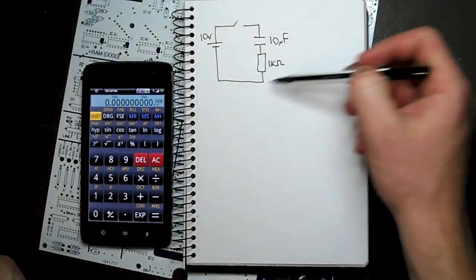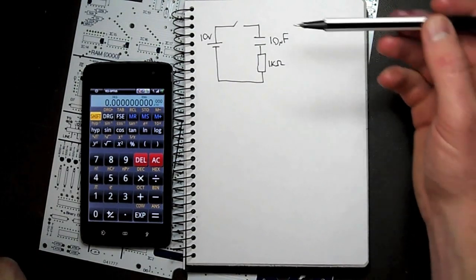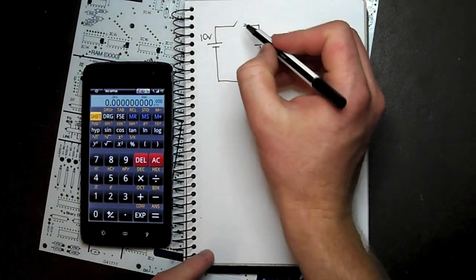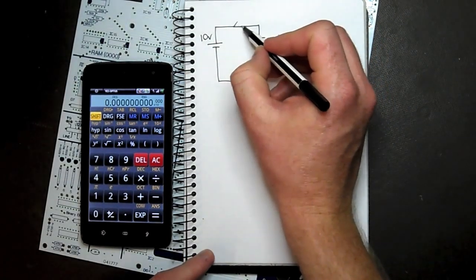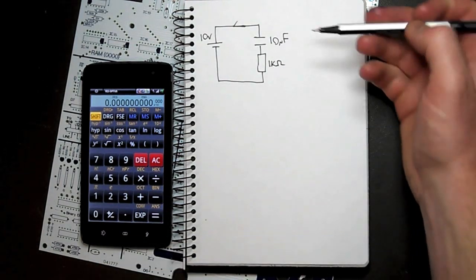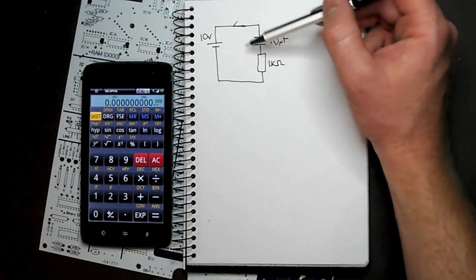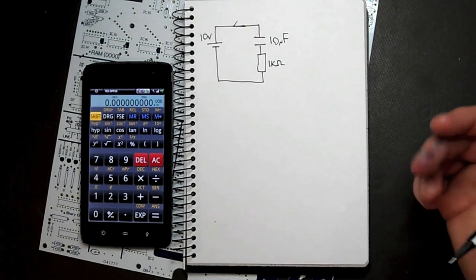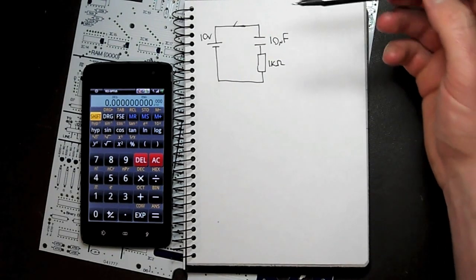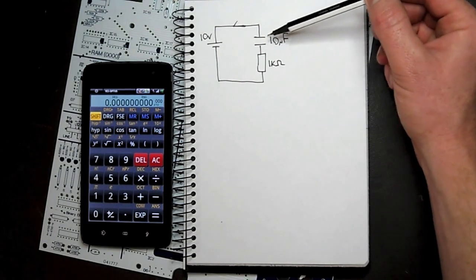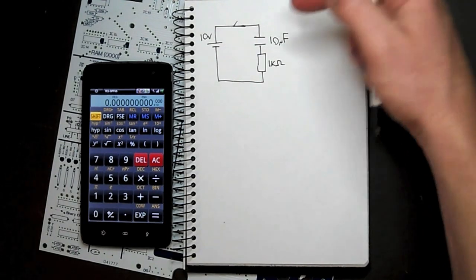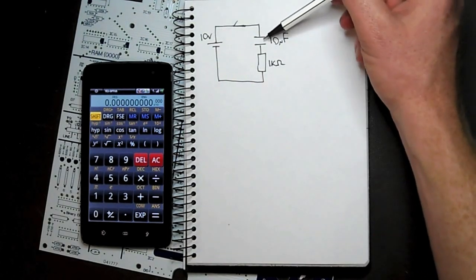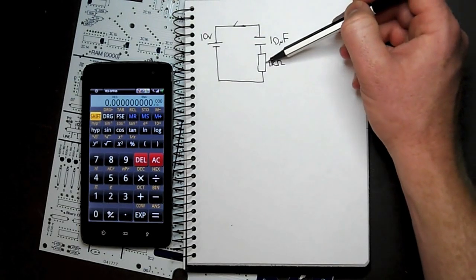Now I've just repeated the circuit here on its own page. But as the capacitor charges, something interesting happens with our circuit. So let's close this switch. We've now got a complete circuit. As soon as we close that, this capacitor was still discharged. Remember, it needs 5 time constants to charge up. It needs time. When we first close this, it's still discharged, which means it's got 0 potential difference. So 0 volts will be across that capacitor. If we've got 10 total, and this is grabbing 0 of that, then that leaves 10 for here.